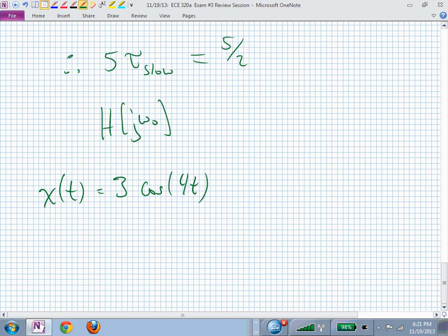But I sort of gave you a trick question. Because on that pole zero diagram, did I give you a gain or a magnitude value for H? All you know are where the poles and the zeros are. I didn't tell you what the gain was. I would have to tell you one more piece of information before you could answer this question completely.